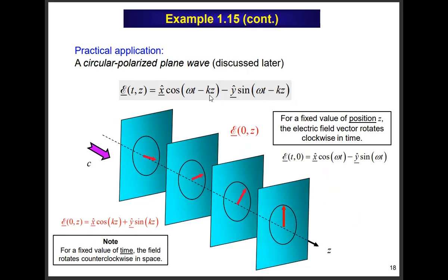like this. Now, it's got two components, X and Y, and the third component that's missing, Z, would be called the direction of propagation, the direction the plane wave is going in or carrying power. And of course, it's propagating at the speed of light because it's a plane wave going through space. Okay. Now, don't worry about where this equation comes from. That'll be solved for later in the semester. Let's just pretend that's the electric field as a function of time and distance Z.